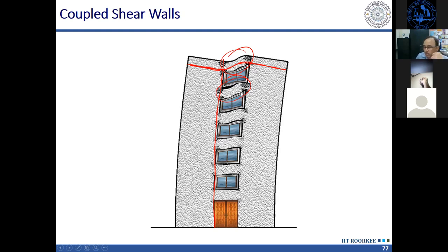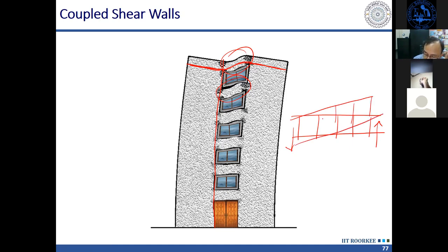So you remember in our normal reinforcement detailing for shear force, what are we doing? We are having longitudinal reinforcement and vertical reinforcement, and this arrangement is resisting vertical shear force. Now, you may think how this arrangement can resist vertical shear force, because it can deform like this. Why does it not deform like this? Because there is concrete here. Concrete acts like a strut, so concrete completes the truss, and that's how it is able to transfer the load.